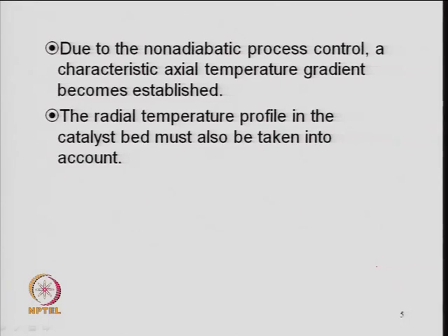Again, due to non adiabatic process control, the characteristic axial temperature gradient is established. Whenever you have an endothermic or exothermic reaction, because the conversion is increasing down the length, the temperature will rise if you do not control that.